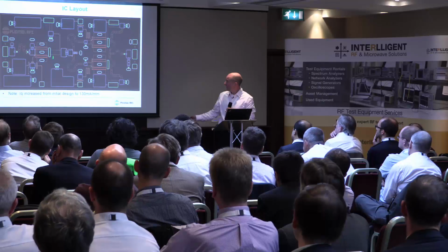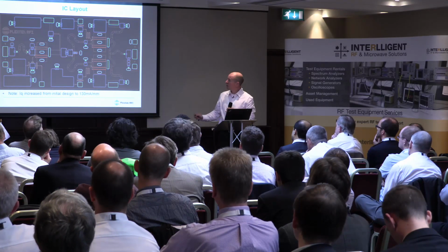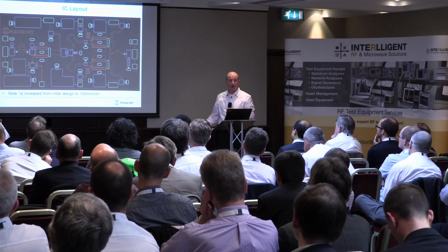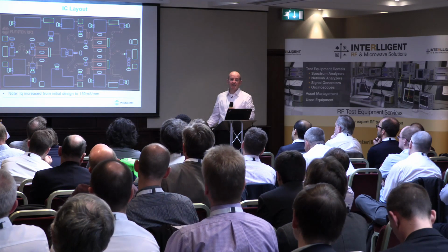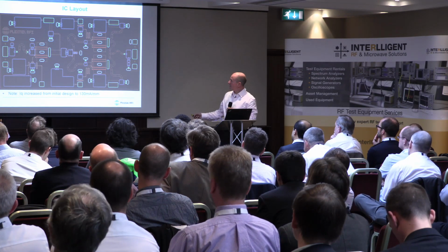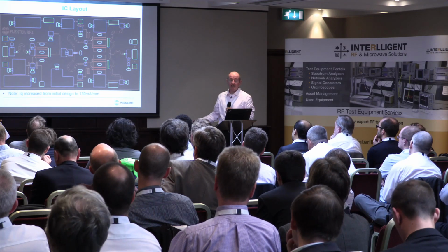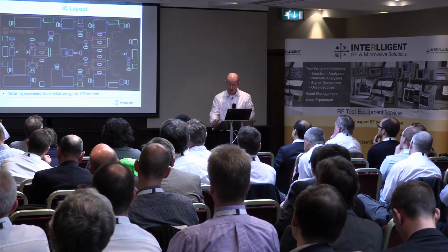The input stage is actually the same size as each of the output stages. Now, if you were just interested in PSAT, you could have made this smaller and got better efficiency from the complete amplifier. Because we're interested in linearity, we want to make sure that this input driver stage has not started to compress at the same time as these output stages.